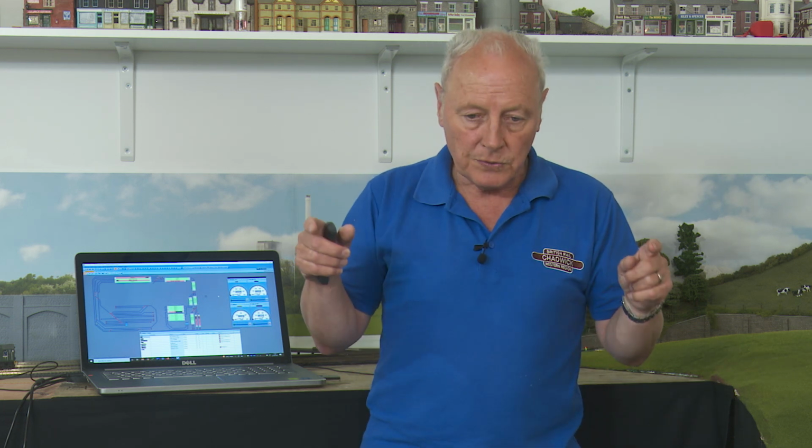But why would you want that? Well, quite simply, if you're in single direction running, the train would come onto the block. But if the next block were to be occupied and you want that train to stop, then you have to start specifying orders to the train so that the DCC decoder will understand what it's got to do, because you will specify in the block how far you want it to go and then when you want it to stop, to save it running out of that block and crashing. And this is how it's done.